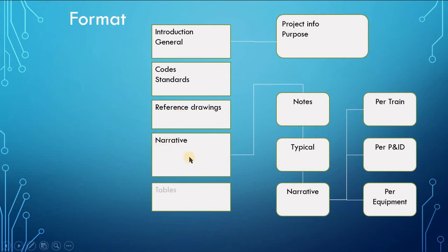And the second thing now is your narrative. Now, what is your narrative? You can start it with a note again to the programmer. You may tell him again that in stage 1 pump X and pump Y will not be installed, but you have to program it in the system, and to avoid an unnecessary alarm, the operator cannot select the pump which is not installed.